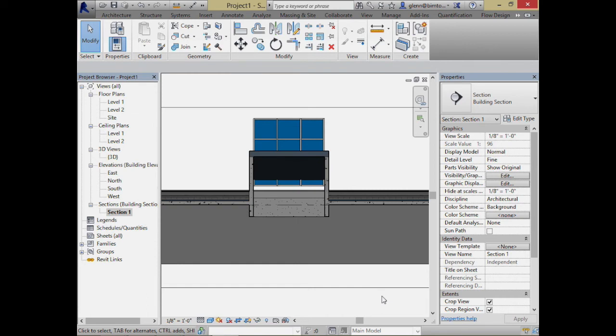So what about just under normal circumstances? Not like a disaster happens, but under normal circumstances, will Revit figure out about how much the dirt and the plants weigh? No. What it'll do is we're going to have to, as good engineers, just plug in our assumption about what we think is reasonable. So maybe we want to assume 18 inches of standing water. But we'll figure that earth, when it's marginally wet, but not soppy, we'll make some assumption, not for the 100-year flood, but for something that we consider to be a reasonable engineering judgment.